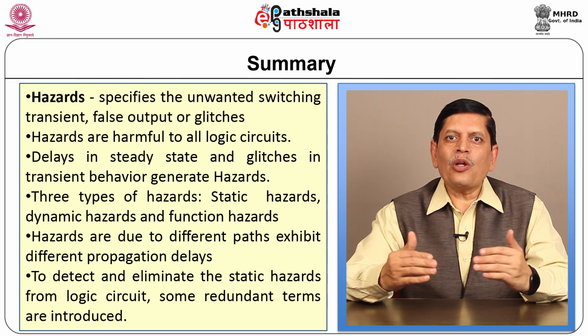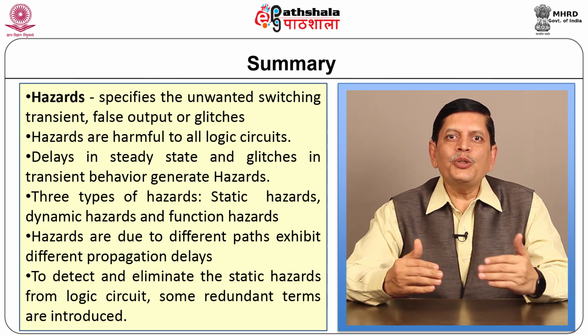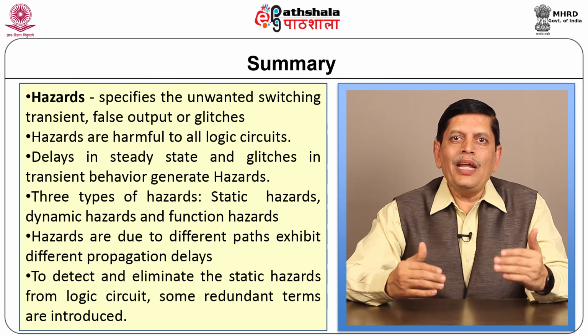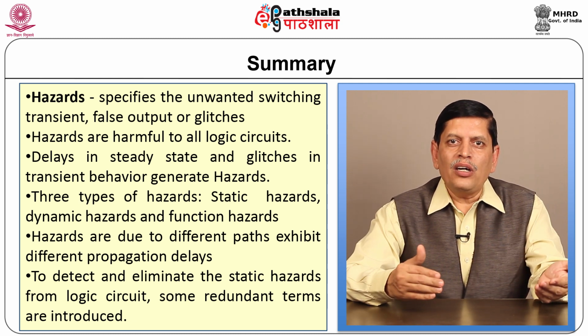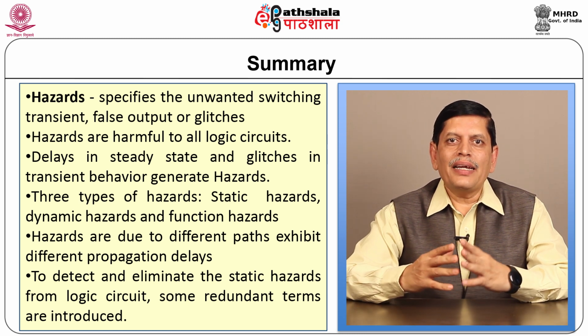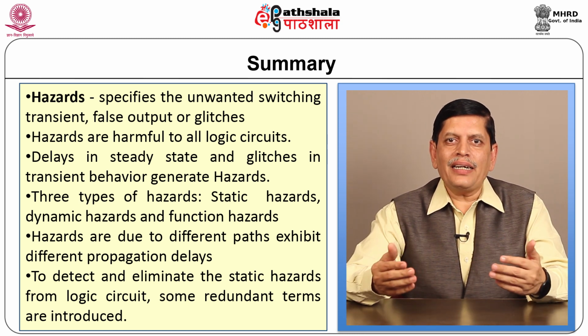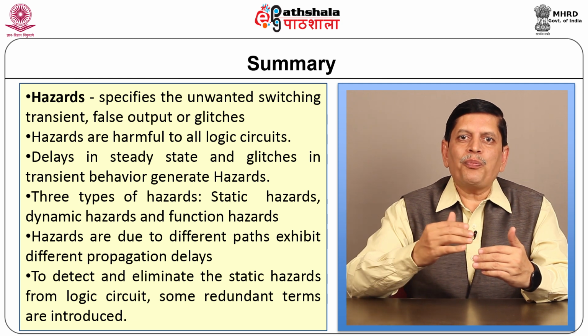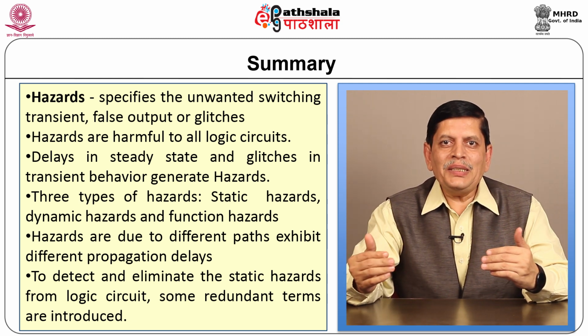Now, the solution to the static hazards is to use some kind of 2 level logic gates, either AND-OR or OR-AND circuits.